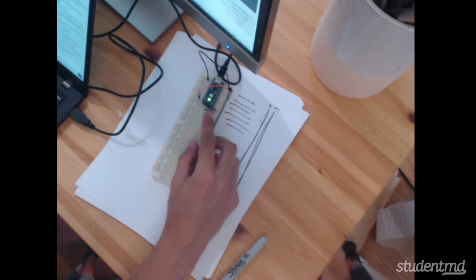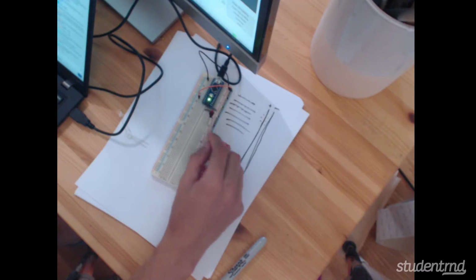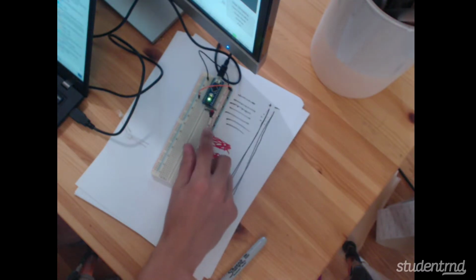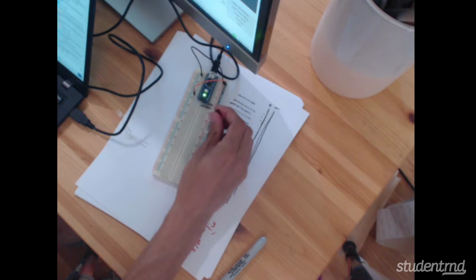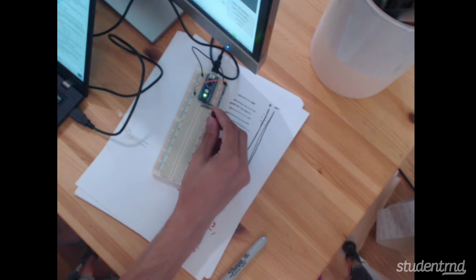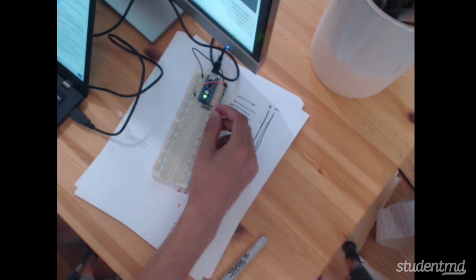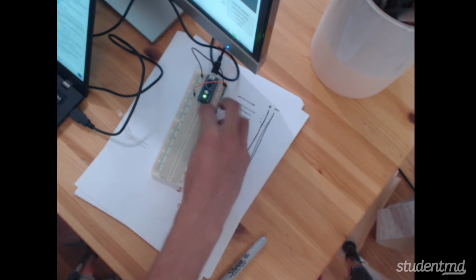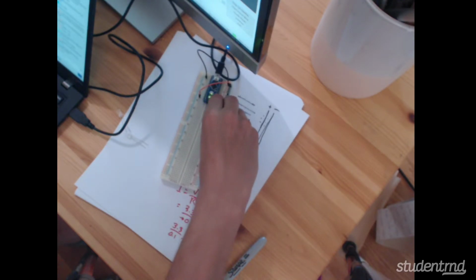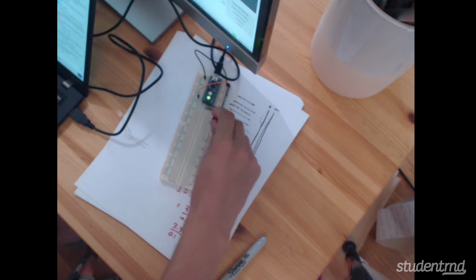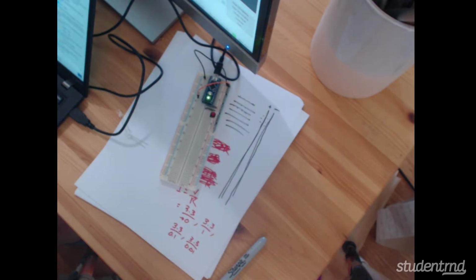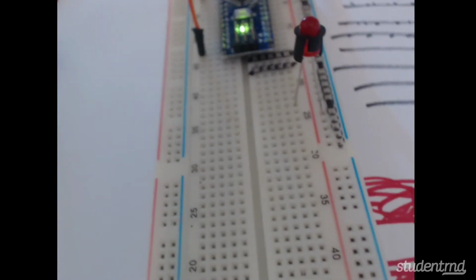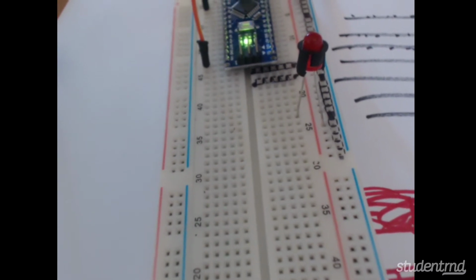And I know this is a little bit hard to see. I'm going to do my best. But what we're going to do is connect the positive side of the LED, which is, again, the longer side. We'll double check that, and it lights up. So the longer side of the LED is the positive rail, right there. And we're going to connect the negative side over to one of these rows. Let me see if I can get a little bit closer view of that. Again, I apologize, but you can see it's one of these rows.